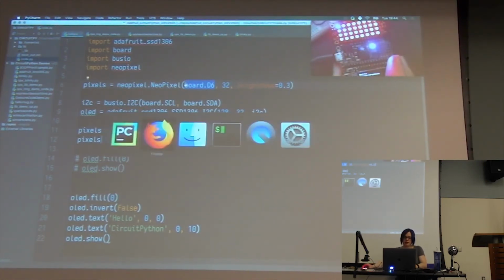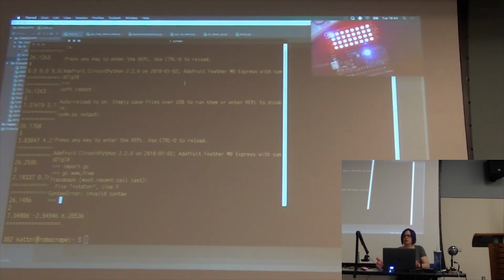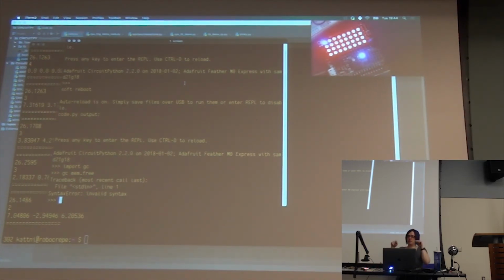Notice the status LED is white. The NeoPixels are just strung together on a single serial link. That's why there's a library, I don't know if there's one for this one, but there's a library for the DotStar one that makes it pretend that it's a grid. So you can tell it to do things on the grid instead of going, okay, I want 1, 7, 16, 22, and 48 to light up. You can say I want row whatever and column whatever, and then it does it. And again, that was written by somebody who wanted to be able to do that, so they did it.